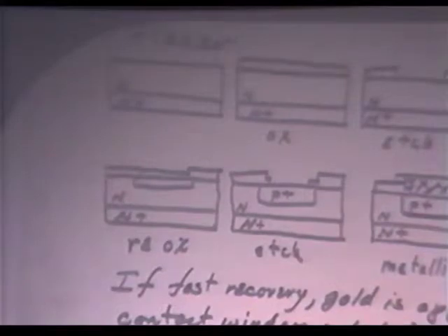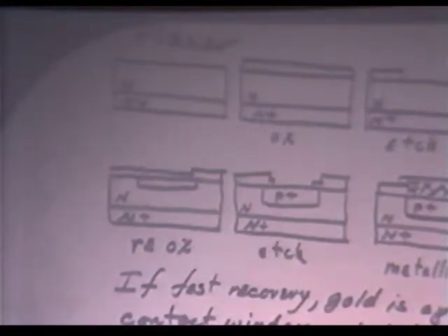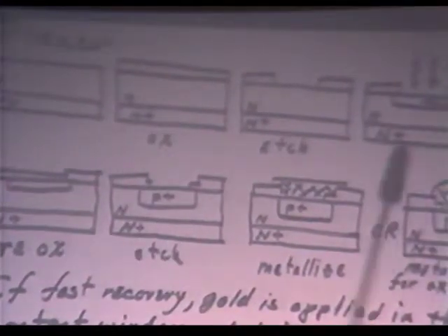Now, we regrow oxide here and then cut a hole in the regrown. Generally, I am told, at least at this level of complexity, that's to be sure we have, I was trying to think of a good buzzword and I don't have one, enough clearance laterally here between the edge of the passivating oxide and the point where the junction comes to the surface. That's particularly true if you do shallow diffusions, because the distance it goes out this way is in proportion to how deep it is. So, at any rate, at this point we do have a diode we can access.